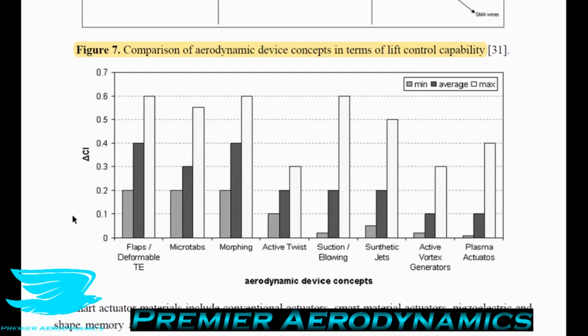And likewise, plasma actuators, let me explain plasma actuators briefly. So plasma actuators are often there to delay stall. That's one of the main mechanisms. And how they do this is by introducing a high momentum flow very close to the surface in the boundary layer. What that does is it re-energizes the boundary layer so that it can continue to flow over the airfoil, the suction surface, when you have an adverse pressure gradient.